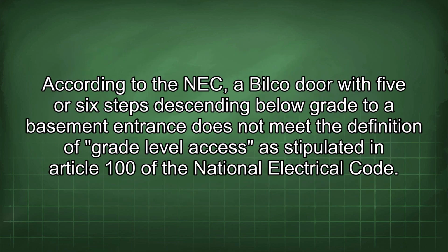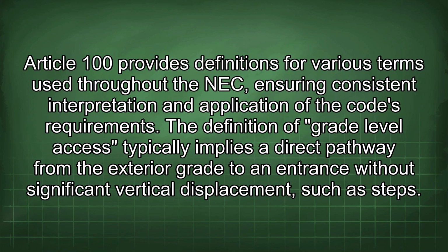According to the NEC, a Bilco door with 5 or 6 steps descending below grade to a basement entrance does not meet the definition of grade-level access as stipulated in Article 100 of the National Electrical Code. Article 100 provides definitions for various terms used throughout the NEC, ensuring consistent interpretation and application of the code's requirements.